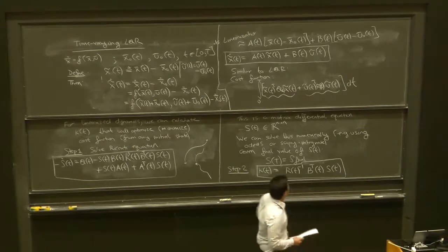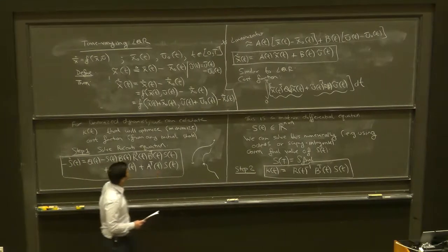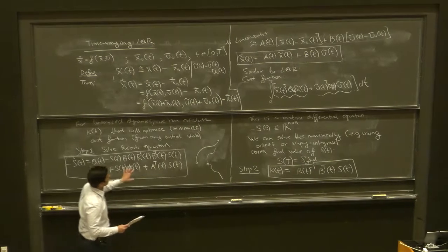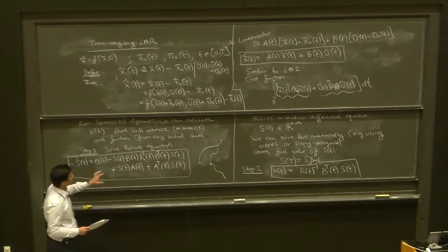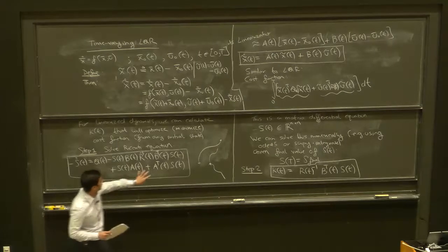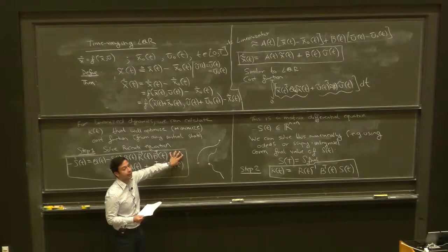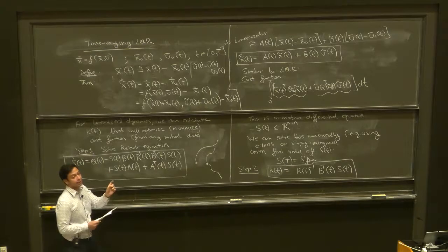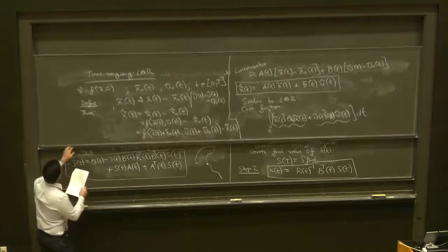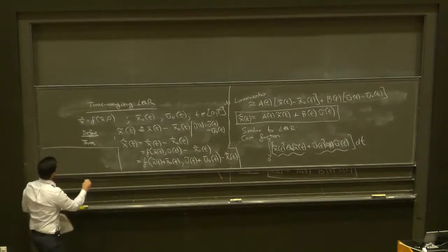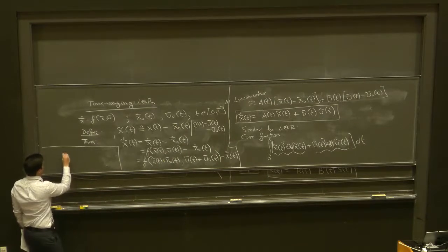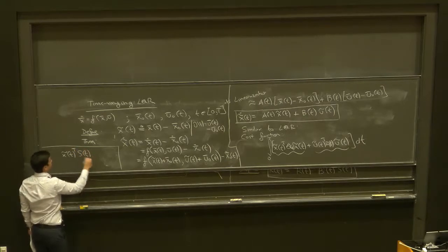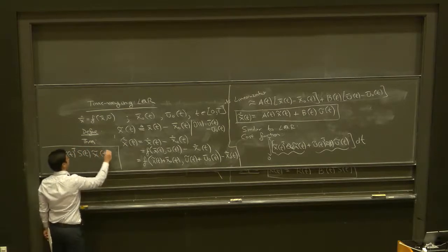Yeah, so the semantic meaning is, okay, I guess I didn't discuss this here, but if you remember from our LQR discussion, this S at time t has a physical meaning, and specifically x transpose S x is the cost to go. So maybe I'll write it here. If I give you some state x tilde at time t, you take the transpose, multiply by S, multiply that by x again.